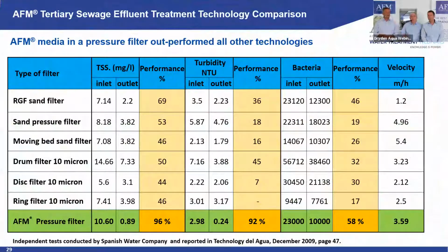And of course, you can have different methods to remove suspended solids, like RGF sand filters, pressure filters, moving bed sand filters, different drum disc filters. But all of them have different performance of suspended solids removal. Here in this table, you can see the performance.